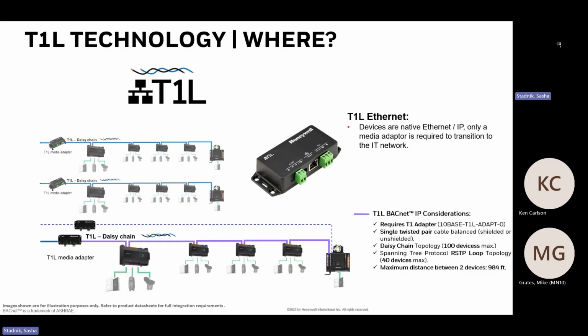But this device is not a gateway. This device is a cable converter. It doesn't use any IP, so you don't set a MAC address in here. You don't set an IP address in here. You don't set a subnet mask. This is completely invisible in the system.